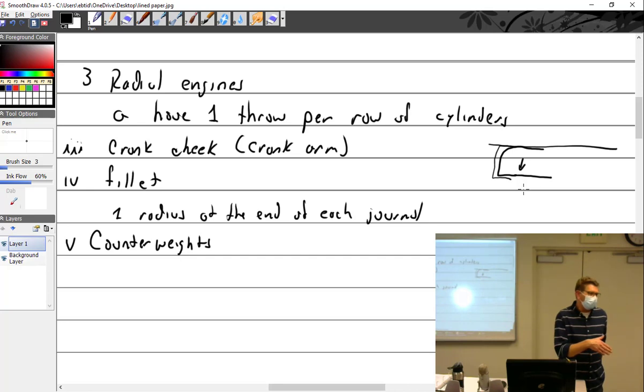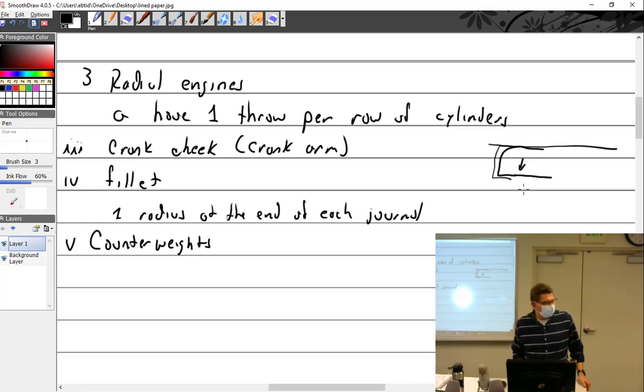And so something that has a 1st order counterweight means it's taking out a vibration that happens every revolution. A second order is every other revolution, and a third is every third. That's all it is. But that takes out all the pressure pulses. And I think that's why it's so important, especially on the 6 cylinders, because the shafts are getting pretty long and they want those vibrations taken out. I'll tell you, I fly behind a Continental 6 cylinder, and it's just remarkably smooth. But I also thought Lycomings were too.